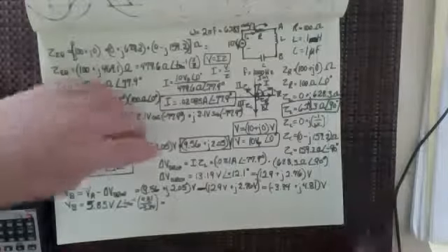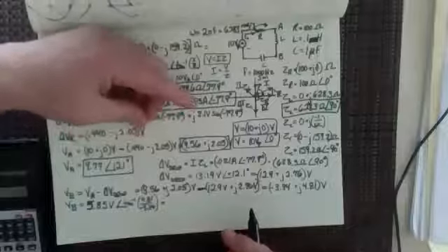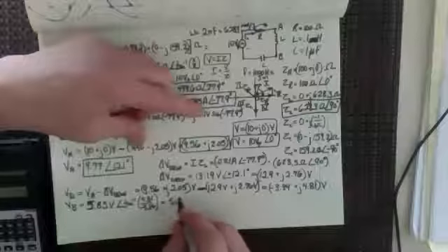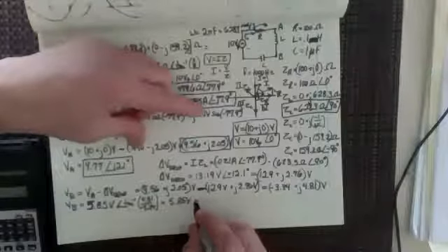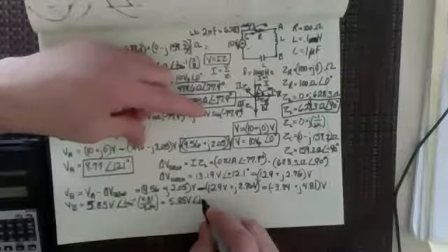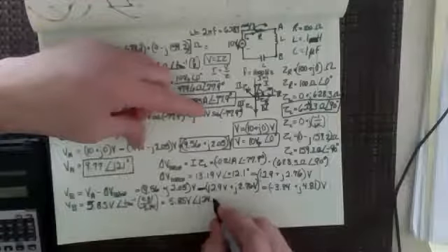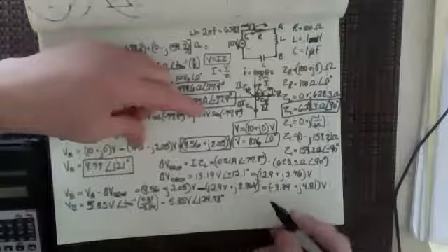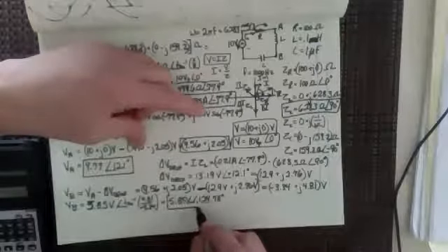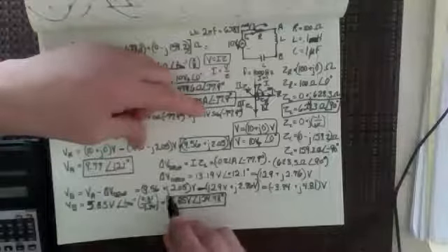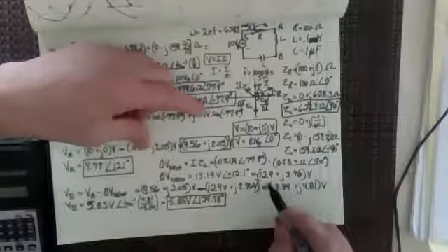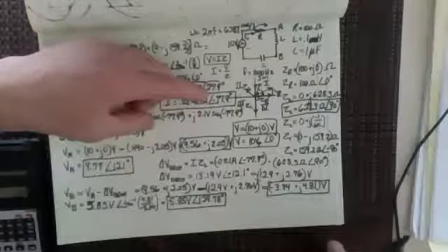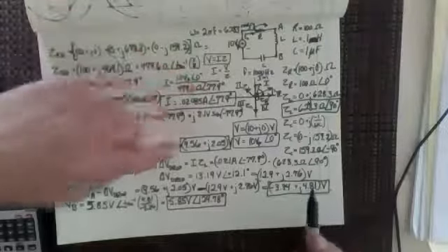And that then gives me an angle of 124.77. So this would be 5.85 volts at an angle of 124, well, let's just say 78 degrees. So that would be our voltage at B in phasor form. And of course, we have our voltage at B in rectilinear complex number form too. And I've got the A there.